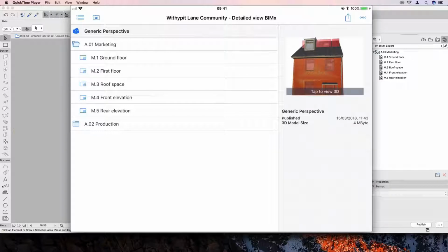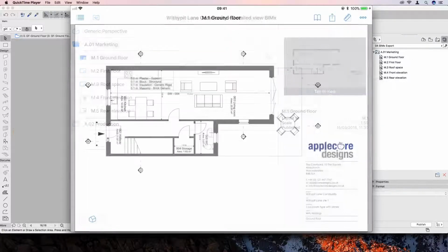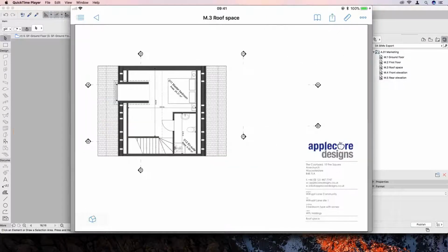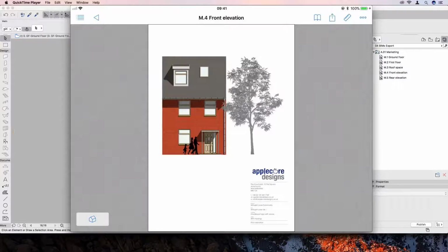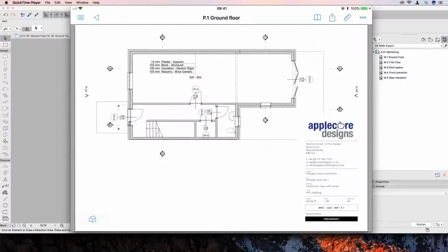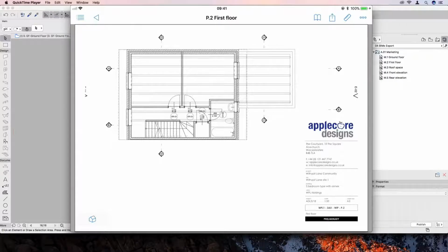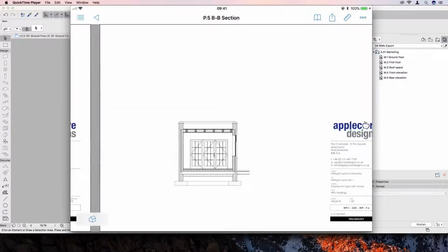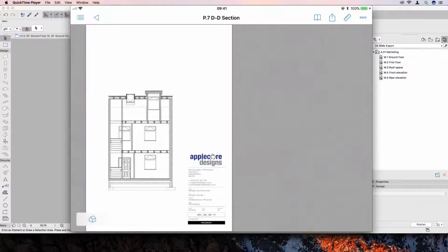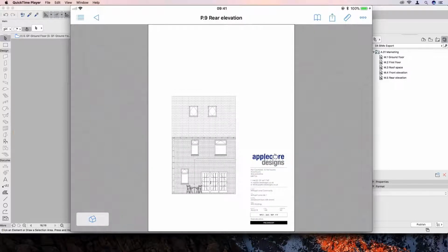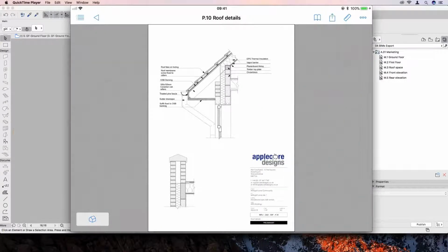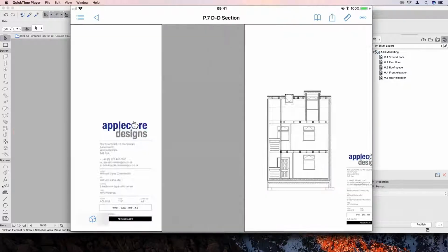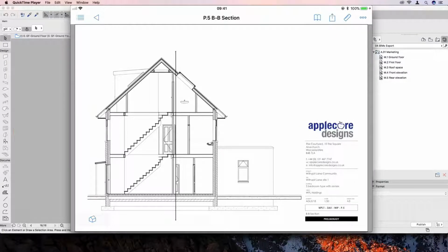And you'll see here, if I click on any of the points, as Sean showed you in the ArchiCAD file, we've got things like ground floor information. As I say, if I move across the stylized view, all this is controlled by yourself, how much information is sent across. We then start to look at section information and things like the schedules can be brought across here as well. We can also have different styles of things like sketch options and then right through to the details. So as I say, this is just one of the house types. You could send a model out per house type to the client if you wanted to.